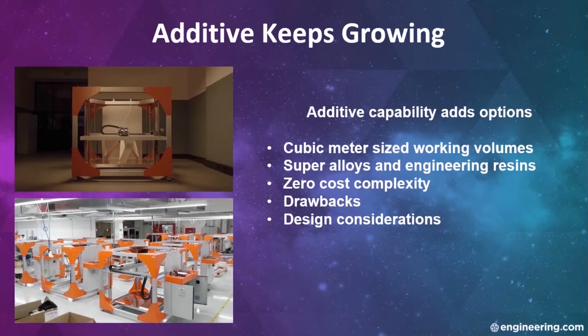Now, the same rules apply, with speed defined by the metal deposition rate. Well, it's inversely proportional to the quality of the surface finish. For some architectural applications, surface finishes are not a factor, or they might even be advantageous. But in most large assemblies, a post-build finishing step is a necessity, and it might be labor-intensive for complex and organic shapes. There's an exception in some heat exchanger engineering where that need to break laminar flow on cooling channel walls benefits from a rough surface texture.